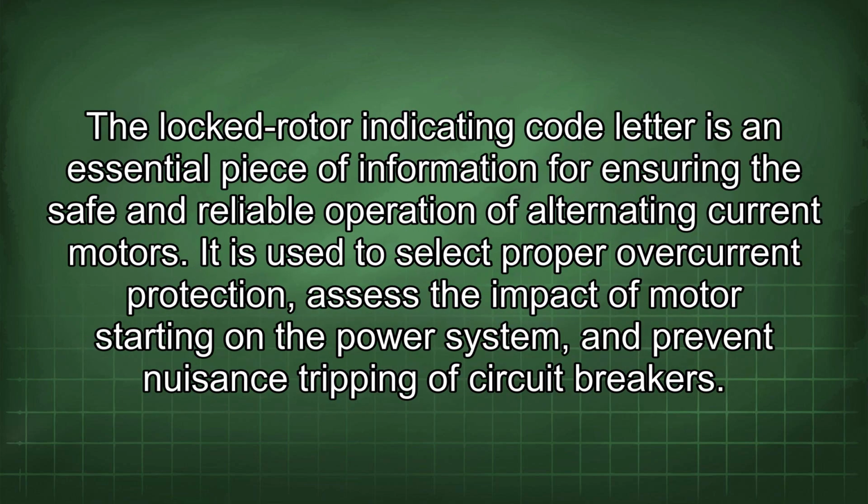The locked rotor indicating code letter is an essential piece of information for ensuring the safe and reliable operation of alternating current motors. It is used to select proper overcurrent protection, assess the impact of motor starting on the power system, and prevent nuisance tripping of circuit breakers.